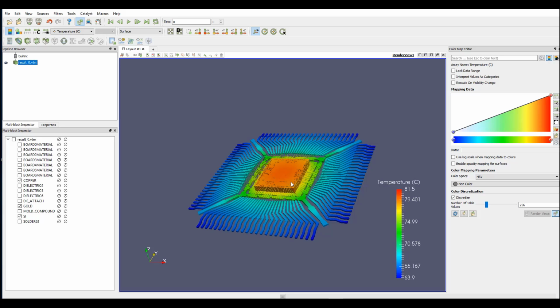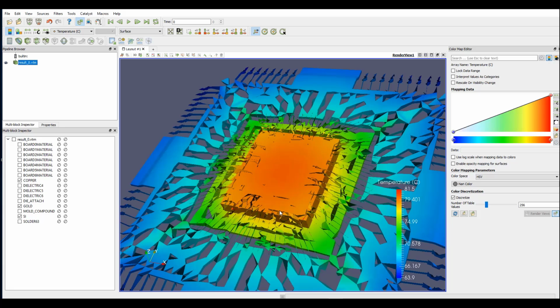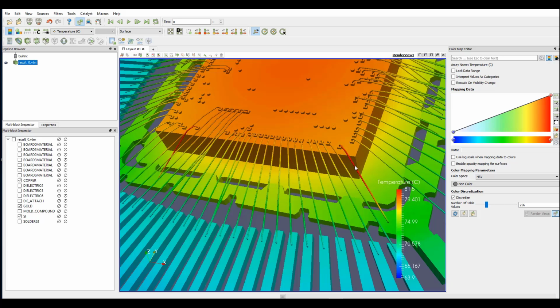See, in this case, you can see apparently the designer pumping the high current going through this wire and coming out of this wire. Then we can see two wires because the electrical or joule heating introduces additional heat sources. So actually the hotspot is on those wires.